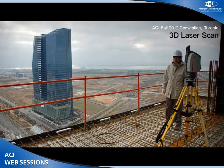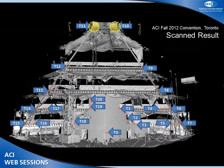Like the KELCC project introduced earlier, I-Tower was also digitally scanned, but this time the Sky Garden was scanned 6 times to see the progress of movement during construction. And the scan points were predetermined as shown in this picture to easily process the massive amount of scanned data, so-called point cloud. When the predicted values were compared to the survey results, the difference in deflections at the most concerned 2 points, which is on top in this picture, were only 1/6 inches.